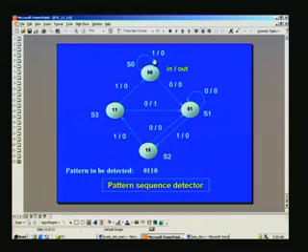So, here the first one is input and the output is the next one, the conditional outputs basically, and we have 4 states here S0, S1, S2, S3, and we will deal straight away with a decimal number instead of a binary number, although binary is put here. So long as 1 is input, we need to stay in the same state, and if it is 0 we need to go to the 0 1 state, and in both cases outputs are 0.